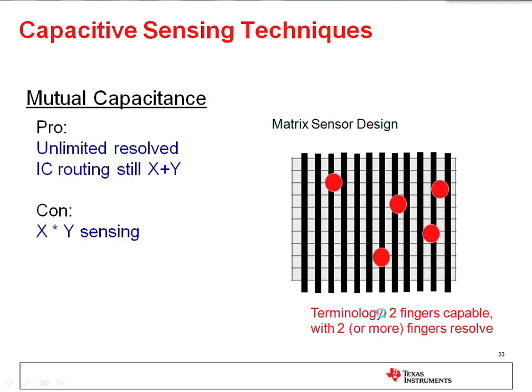So now, in this case, we have basically, again, X and Y detection with multiple fingers, and the initial scan is done with the columns, which detects these different touch points, but then the rows are driven with a voltage, and then it isolates through the mutual capacitance to detect each individual touch point.